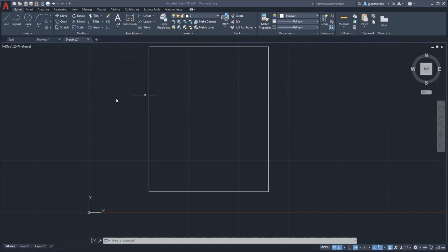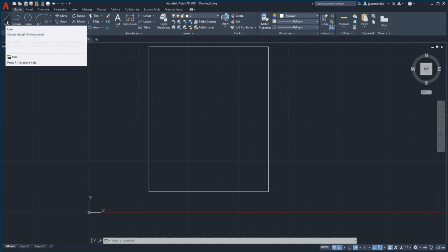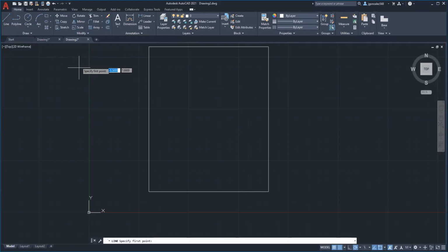I have a question right quick. Sure. For me, I'm able to get the points down, but I'm not getting the lines for the box. So you're using the line command, right? Okay, I hit line command and then... So you hit the line command, and then you type in the points right here. You start typing it in now. Oh, okay. The multi-point is just another way to have a point of reference when you're making your box. That way you know you're hitting the right spots. Oh, okay. I was just hitting multi-point. Thank you. Yeah, that'll only draw little corners. That's it.